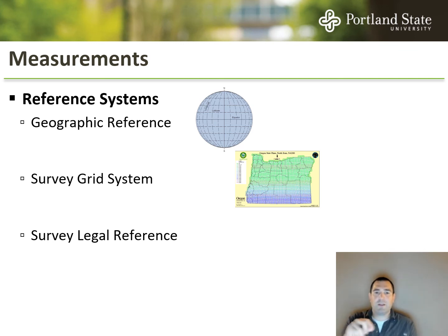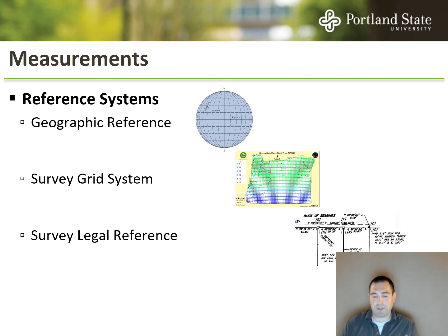The property line starts here, it goes at this bearing for this amount of feet. Sometimes in these old property definitions, it'll say up until this tree or up until this fence, things like that. These are interesting descriptions. That's another way, especially property lines, to be defined: by a legal reference or a legal description. So here's a small excerpt of a property survey.